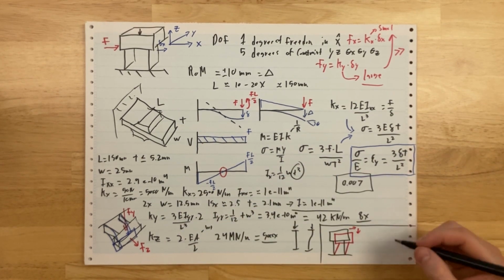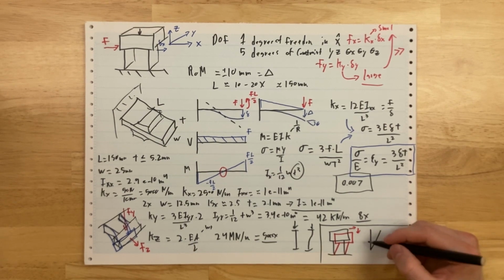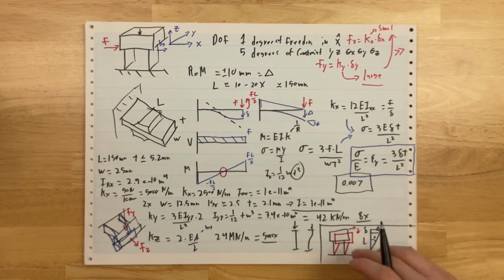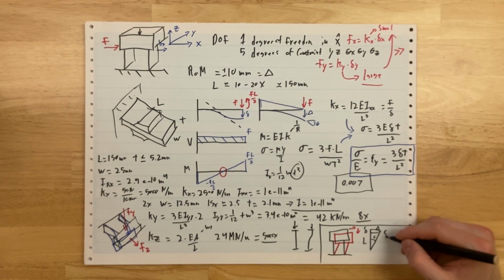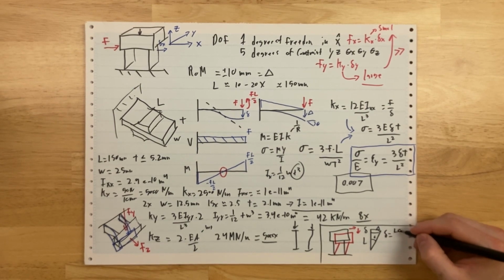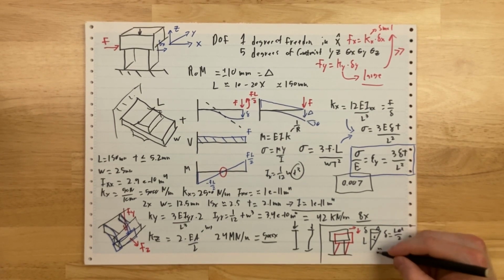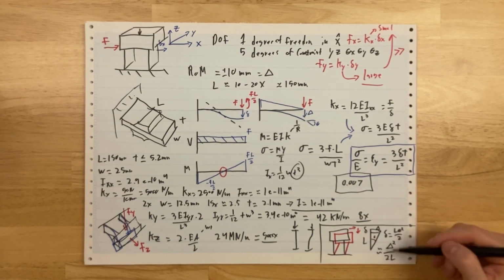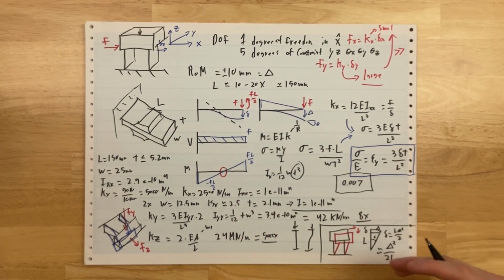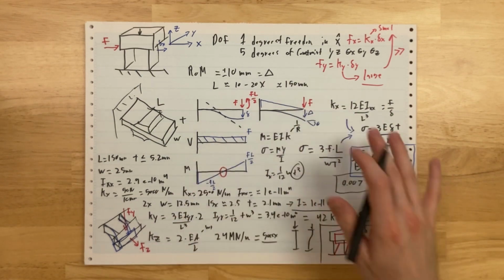How do you actually calculate this? Well, it's basically a cosine error. So here's your length, and it rotates theta, and it moved over big delta, but it dropped down little delta. And you can go through the trig, and you can find that essentially this little delta is equal to L theta squared over 2, which if you plug and chug is also equal to big delta squared over 2L. So it's nonlinear. So for small motions, you actually have very little foreshortening, but as you move more and more and more, you'll find that you're moving in this shallow arc curve.